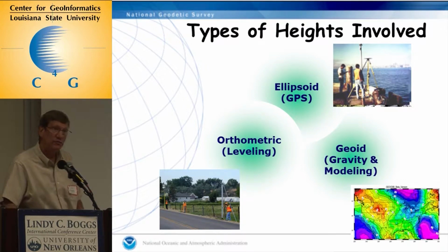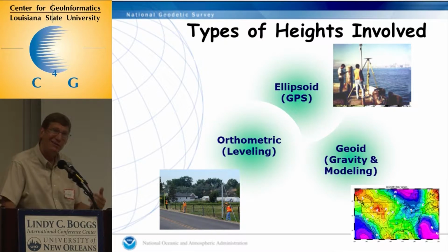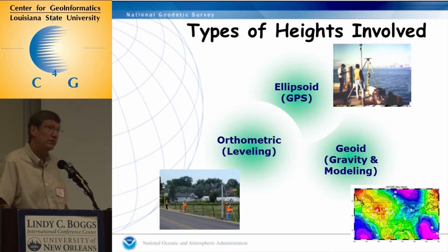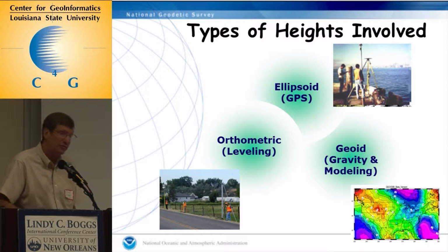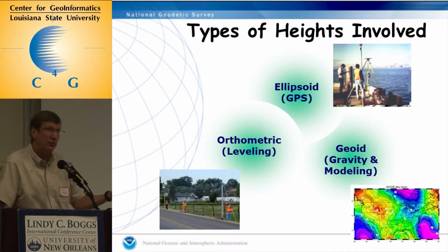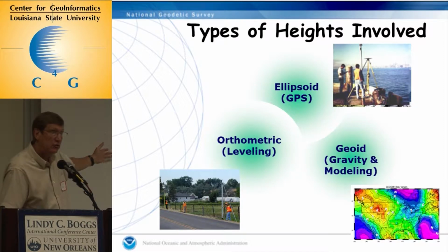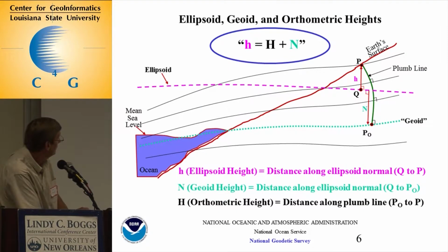But the geoid model still is that little uncertainty, because it's very difficult to really show and prove how accurately I really know that geoid model. And especially in southern Louisiana, where you try to prove how accurately you know it by comparing it to benchmarks, which now have subsided. But these are the critical parts of the meeting today. And then tomorrow, when you're talking about the real time, and you're talking about getting ellipsoid heights, but you ultimately have to end up with orthometric heights, so you have to throw that geoid model into it.